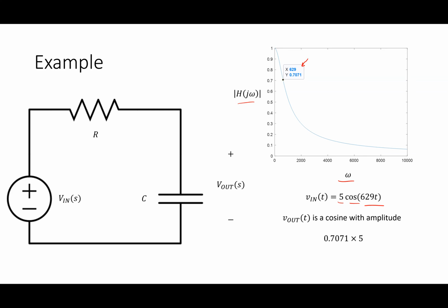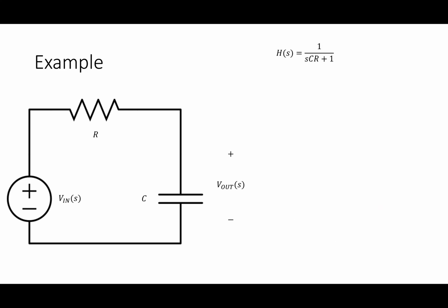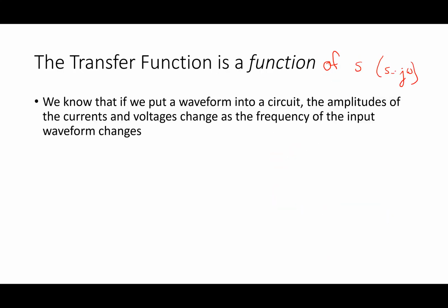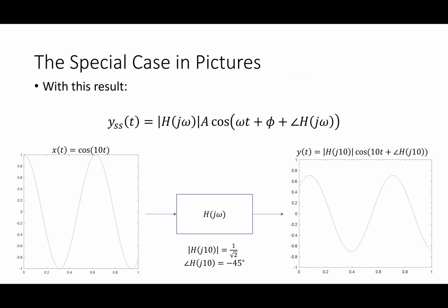That's what that magnitude being 0.707 means. If I was looking at this on an oscilloscope, I would get a picture like what I showed before. My input is one size and my output is 70% of that. It's also shifted a little bit, but the key thing I'm focusing on right now is that it gets smaller. So a low pass filter is basically when your output is less than your input.